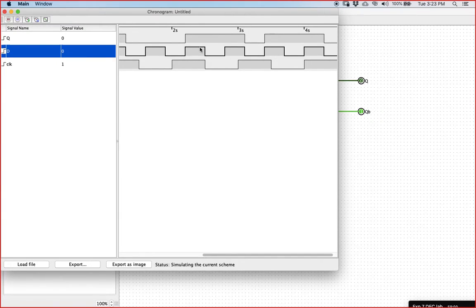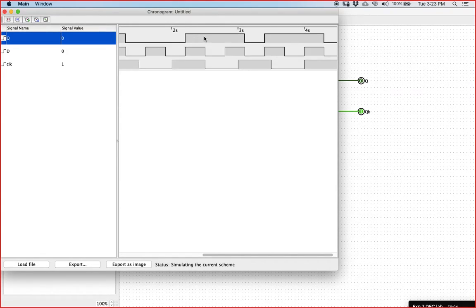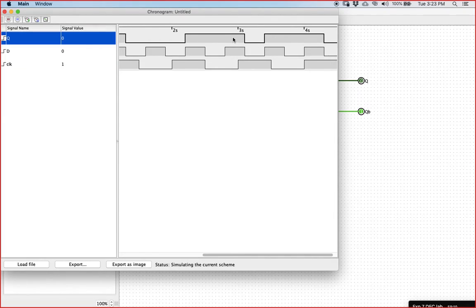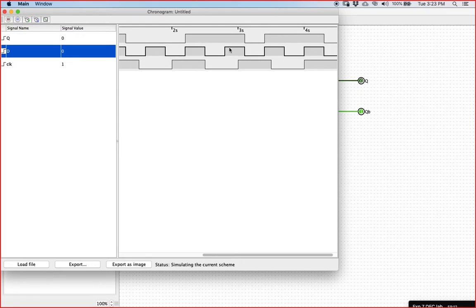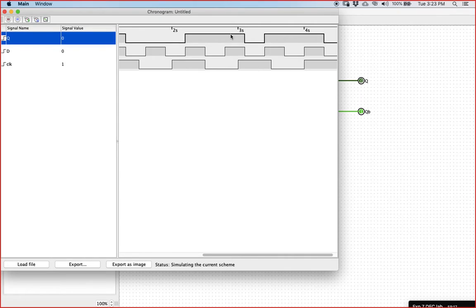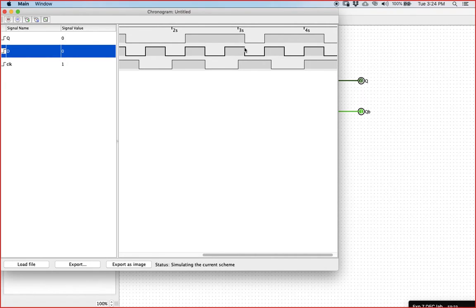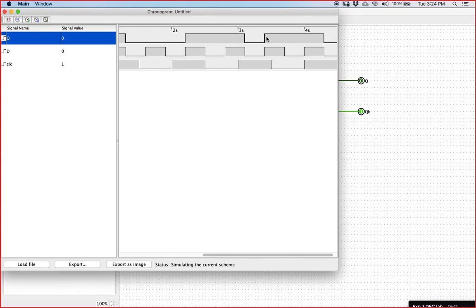So you can see that this was high here, so just before the transition, it stored this value, and so you can see it is high, and from here to here it has kept it high because it's just storing. So even if you see that D is changing here, you can see that it's getting stored. So now after some time it goes high, and it is in transparent state. Transparent state means whatever I have at D here, my Q is the same, right? So you can try to do this analysis.